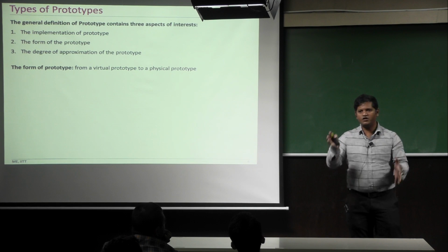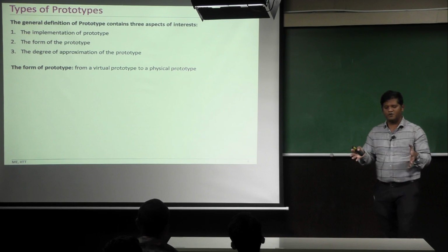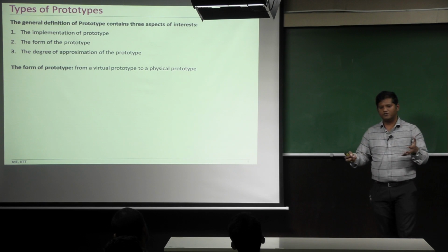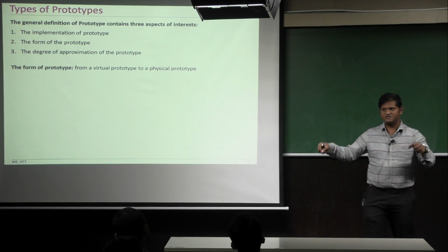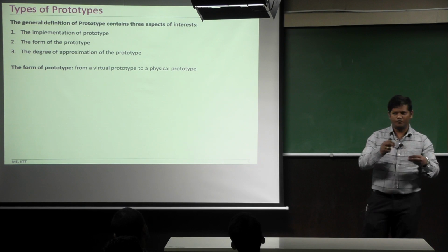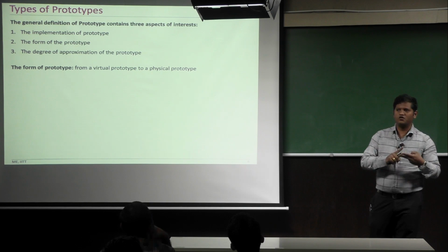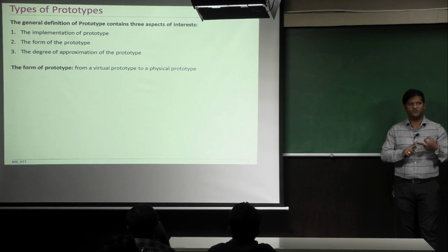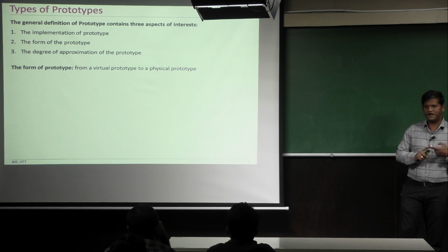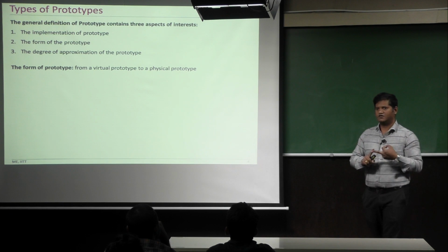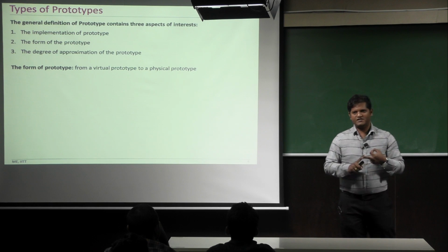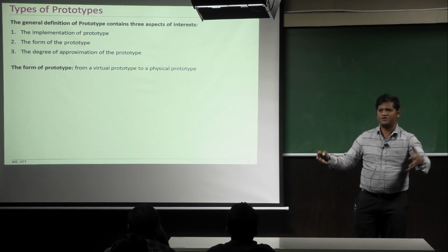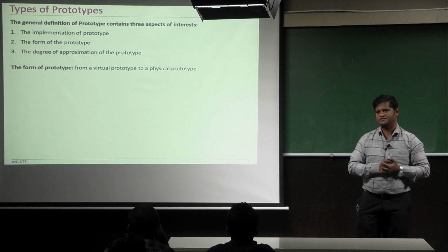Now if you want to minimize the distortion, then one way is to go for a lot of trial and errors. Importantly, there are two things which can affect the final distortion: one is the process parameters, and the second is the sequence of welding. Process parameters and sequence of welding. So let us say you are assembling all the components, you have followed a certain sequence, and you end up with some distortion in the final chassis.